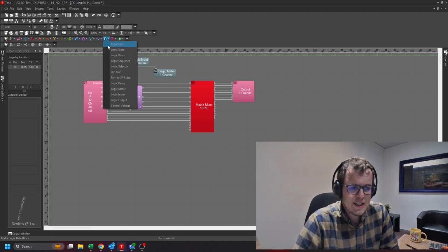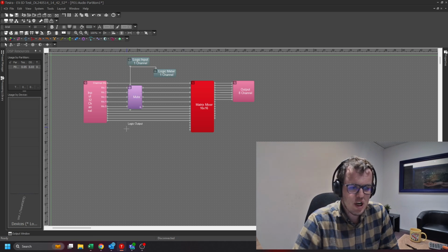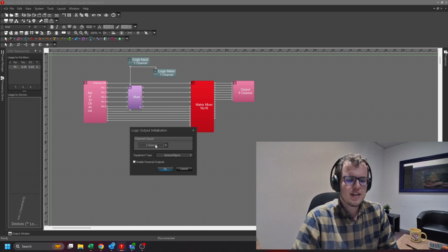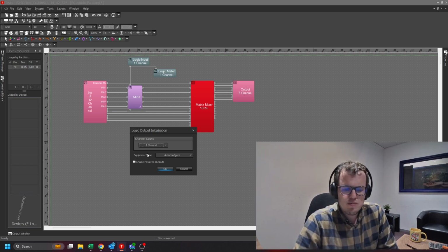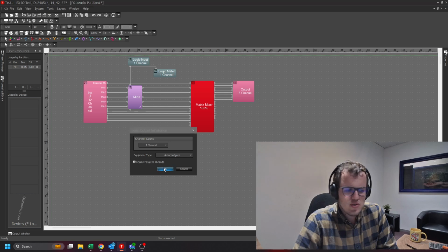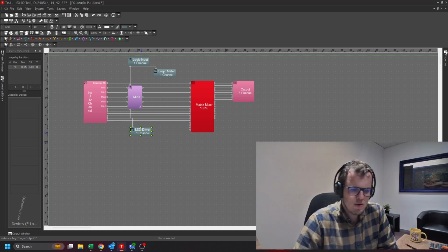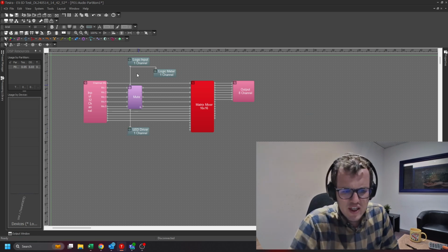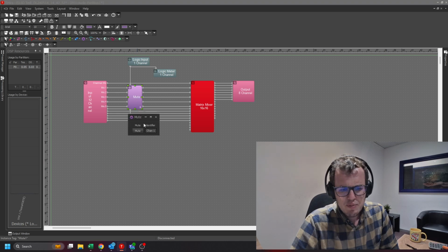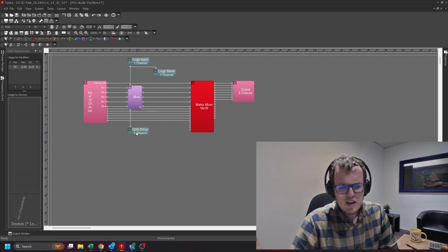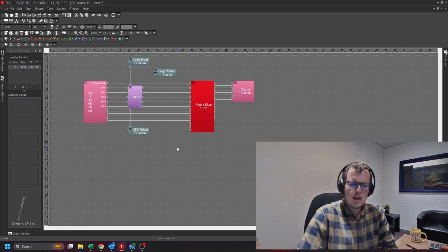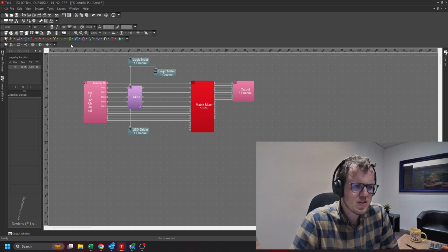And then finally, we're going to be driving the LED out of a separate output, supplying it 5 volts of power to illuminate the LED whenever this block is muted. So on one channel, we enable the power outputs and we attach that to the bottom of our block. That means that whatever is happening with the button, if the block's muted, it will still illuminate the LED ring on the button, and it will always be in phase and an accurate representation.